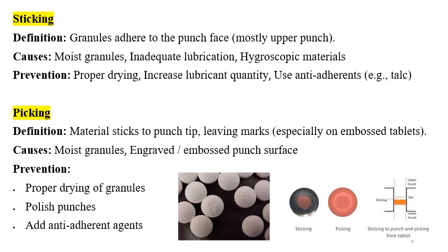Sticking means granules adhere to the punch face. Causes are moist granules if LOD is higher, inadequate lubrication, and hygroscopic materials. Prevention is to get the proper drying parameters, increase lubricant quantity, and use anti-adherents like talc.